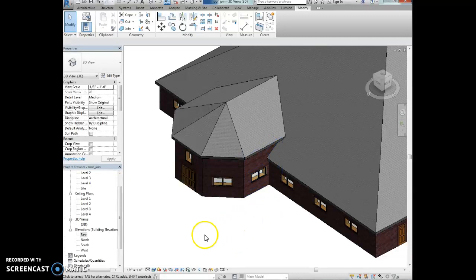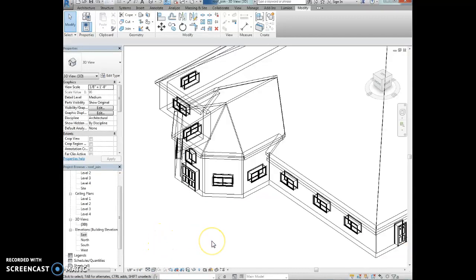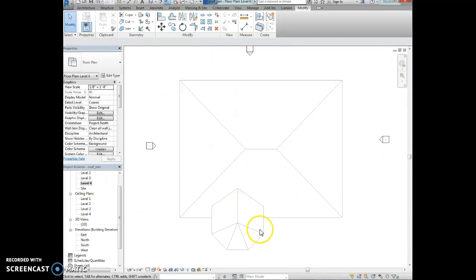And then step number 35 says to eliminate any gaps, to switch to wireframe view. And then you can switch to the top view, so back to level 4 in wireframe. And you can align the boundary of the large roof with the exterior face of the walls indicated.